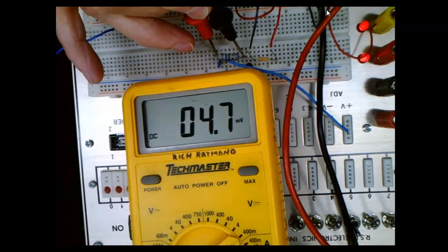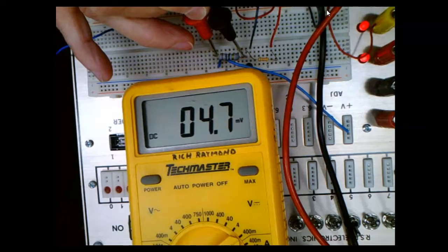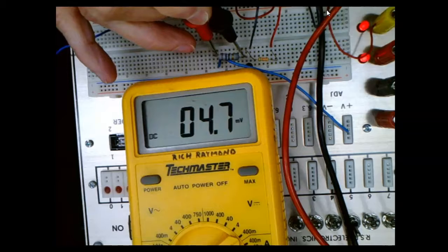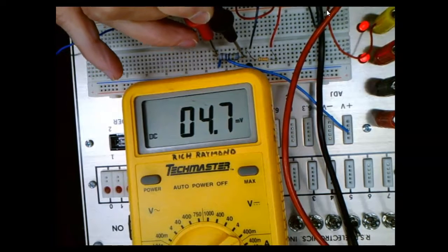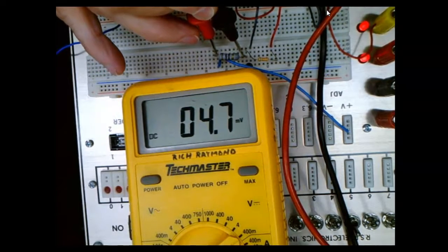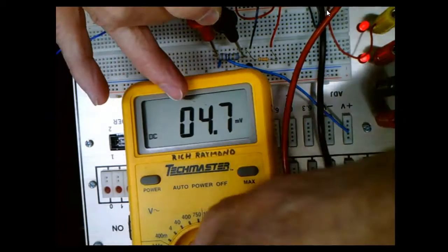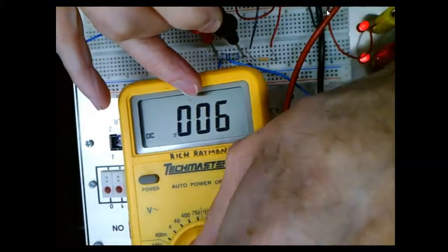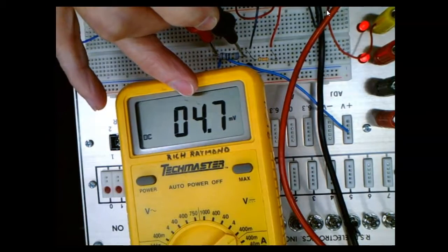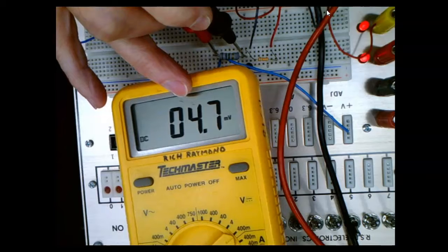Okay. No, VR2. Oh, VR2. Yeah, you're right. VR2, which is the 100 ohm, was measuring 4.7 millivolts or 5 millivolts. Okay, what do I need to do next? You can calculate your IC, right? Everybody got that? Okay. What did we come up with? 500 microamps, 50 microamps.